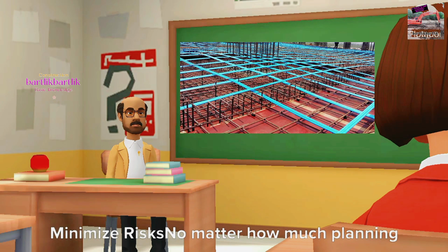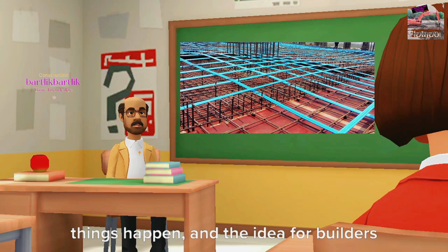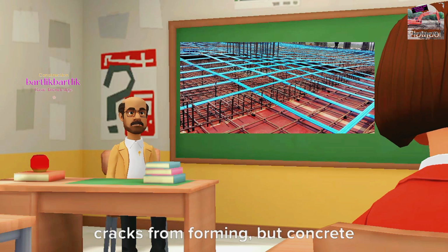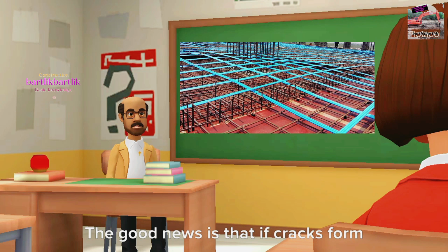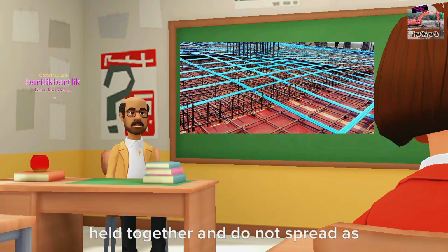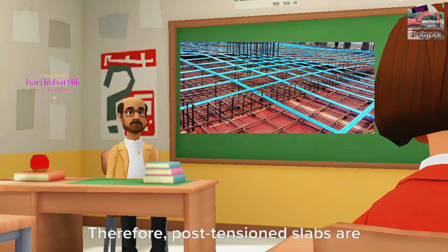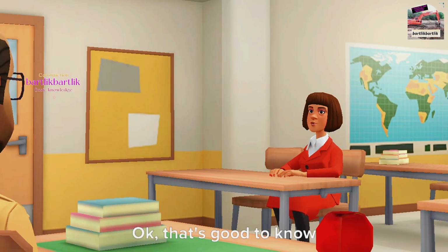Minimize risks: no matter how much planning goes into a construction project, things happen, and the idea for builders is to minimize risks. Post-tension slabs may help prevent cracks from forming, but concrete is not immune to the elements. The good news is that if cracks form on post-tension slabs, they are held together and do not spread as quickly as those on traditional foundation slabs. Therefore, post-tension slabs are a more durable solution. Okay, that's good to know.